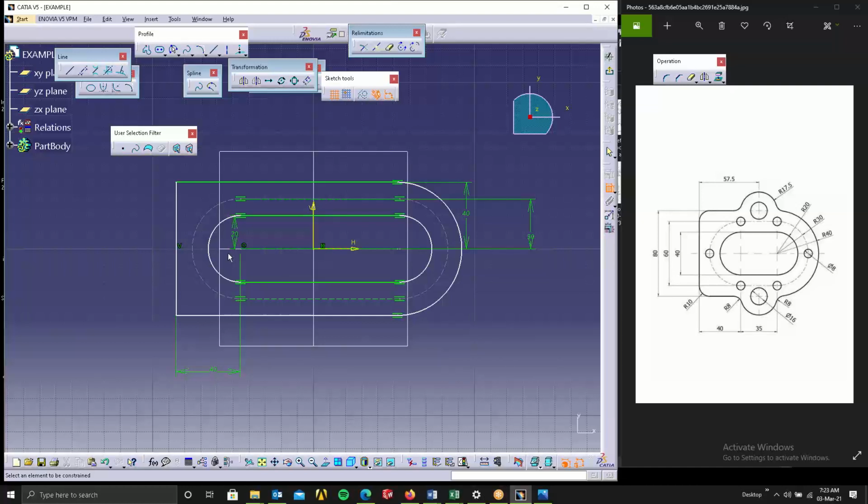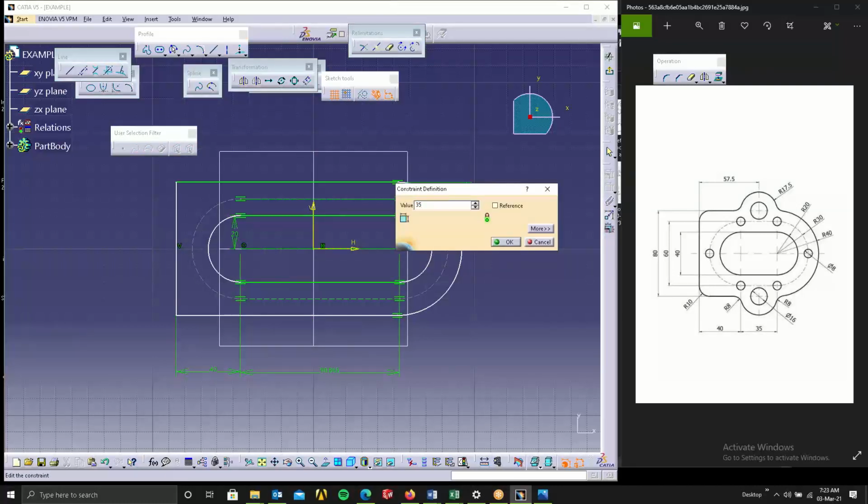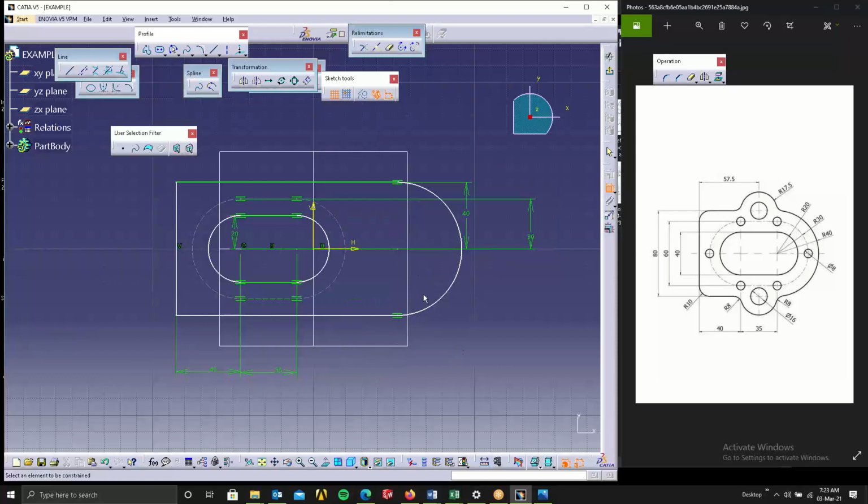That's not going to change. Then we have this length we didn't specify. The central line dimension is 35. Yes, this central line is 35, that is what they have mentioned. So this central line is very small, 35, enter. And same also. You have to just select this endpoint, endpoint. Select this. Coincidence. Escape, escape, escape. Select this and select this.